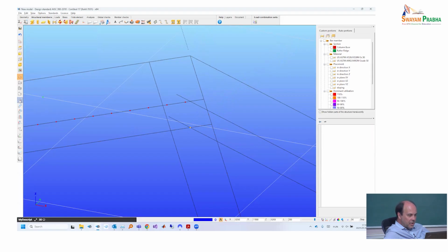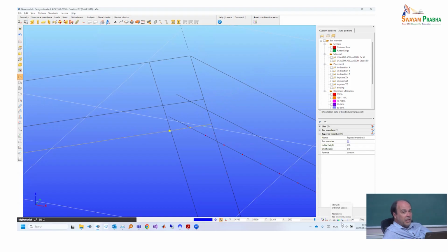So first of all, I need to make sure that my line will really start from the intersection. At the moment you see the line itself is longer, so even if I have this beautiful 90 from the end function, this will start to measure the 90s from here. But I don't want to measure it from here, I want to measure it from the intersection. So first of all I will trim the lines to start really from here.